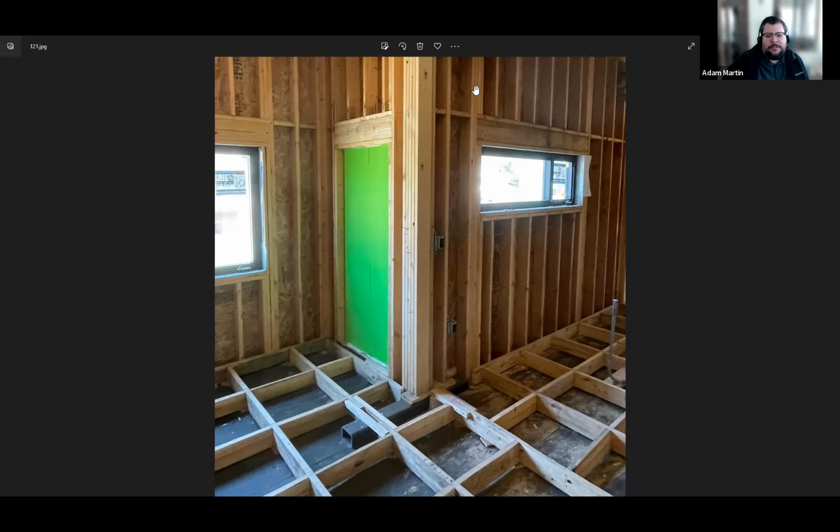I mean, this whole project is an interesting choice, right? Because all your floors are CLT panels, all the way up. Right. So what you're gaining by making this sort of combined load bearing wall and CLT structure is the freedom to make the floor plan layouts at level 2 and up whatever you want, because all the walls become load bearing.